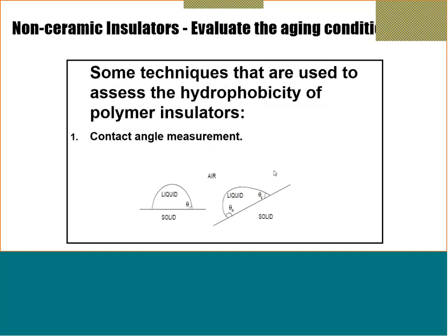The insulator surface, let me start from the beginning. The advantage of silicone rubber, we said, is that it's hydrophobic. Phobic means someone scared of, or an enemy of, and hydro means water. So what does this mean? If I have here a surface of silicone insulating, and this is ceramic, and I put a water droplet here, you will have the water droplets as discrete. Here you will have them like continuous, like this.